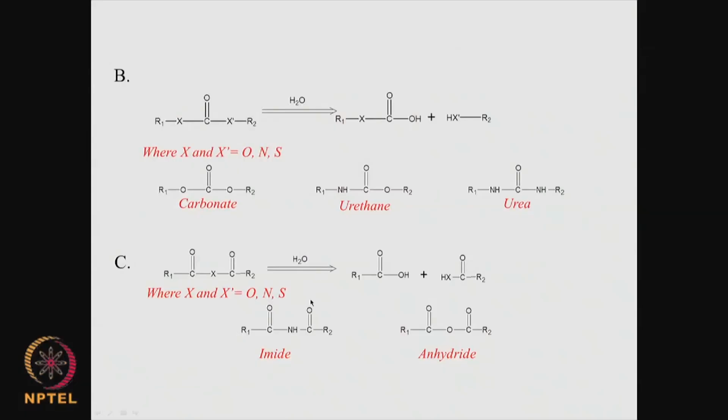So if you are designing polymers with these types of backbones, then they are hydrolyzable, that means they can react with water slowly. And as I mentioned, some of these bonds are degradable at a faster rate, some at a slower rate. So if I am thinking about 2 weeks, 3 weeks degradation, or if I am thinking about 6 months, 9 months degradation, I can design polymers with these different backbones.